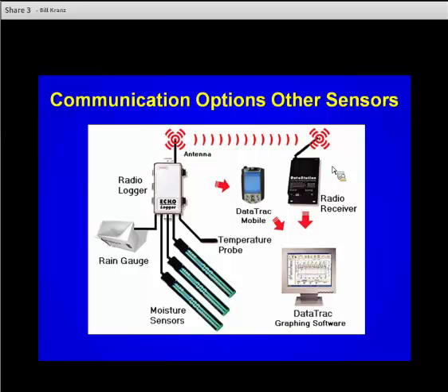These are line of sight primarily, and so crop leaves intercept those transmissions, and if we can't get the antenna above the crop canopy, then we have some telemetry issues. As you all know, the corn hybrids are now 12 to 13 feet tall in some cases, and you really can't put an antenna above the crop canopy and go over it with a center pivot, unless you have a means of causing the installation with the transmitter to move as the pivot comes by.